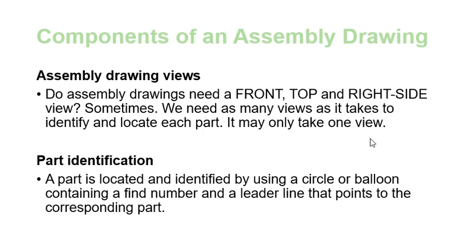so the drawing usually is one view, but then sometimes you might have to put in front, top, and right side view. Depends on what you're dealing with, your system. Because a major point here for doing the assembly drawing is to show the components. So sometimes one view can show all the components. Sometimes you need to put in 1 or 2 or 3 views to locate all the parts in the system. So it depends on your system, how big it is.